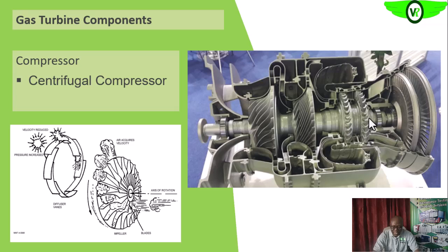So the other kind of compressor that we will be seeing is the axial flow compressor. Remember, in the radial flow compressor or the centrifugal compressor, you see that the air is directed away from the middle towards the circumference of the impeller, so that it will strike on the casing of the centrifugal compressor so as to reduce the speed and increase the pressure.